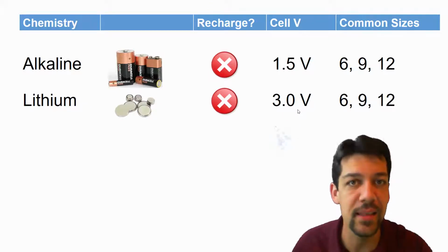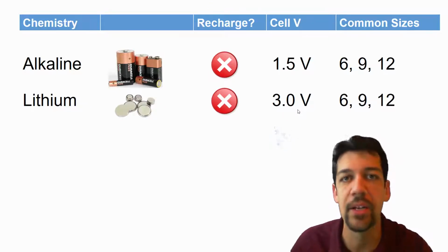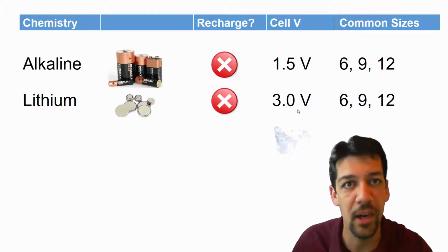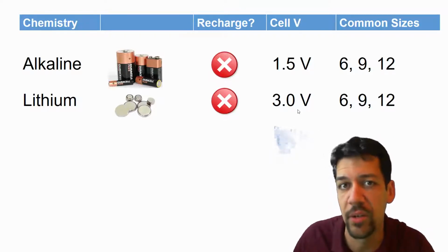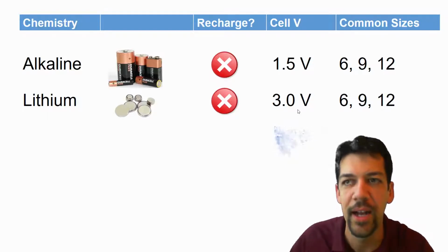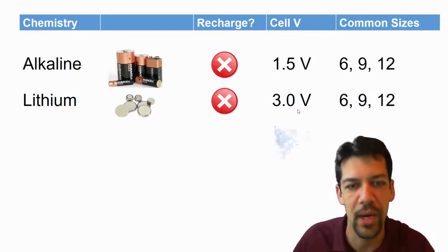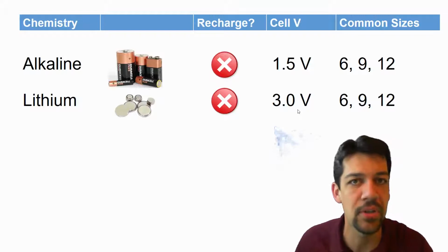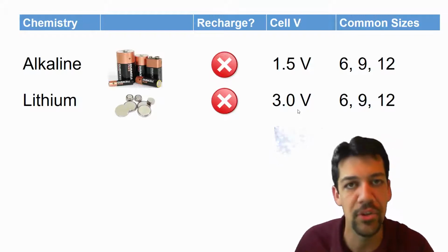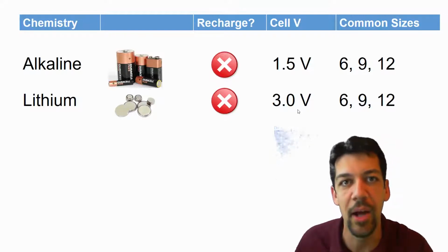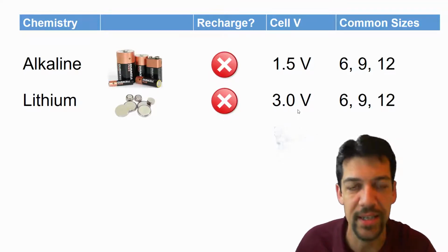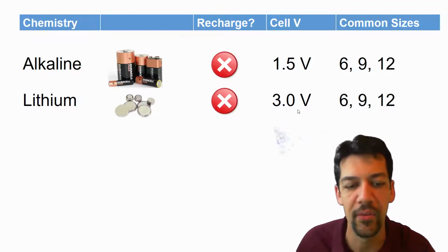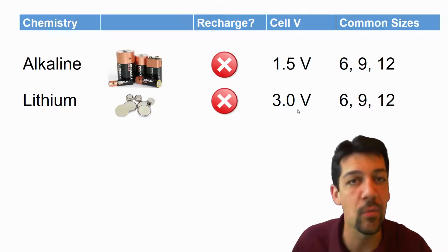We might also see lithium in hearing aid batteries or the emergency clock backup batteries and stuff like that. These you don't see very often. We don't deal with them very often in the modern world, but they're super awesome for little tiny projects and stuff like that. Their typical cell voltage is about 3 volts. They're not rechargeable, but you can get them in bigger sizes, double sizes, so you can get a 6 volt double stack of lithium battery. And these are one and done too.